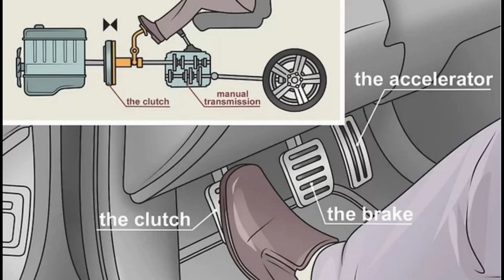Because of its high torque and low speed, first gear is not suitable for fast driving. The second gear provides less torque than first gear but allows the vehicle to move faster. It is often used in slow-moving traffic, gentle turns, and gradual acceleration after starting. The third gear is commonly used for moderate speeds and is well suited for city driving. It offers a balance between torque and speed, allowing smooth movement without excessive engine strain. Fourth gear is used for higher speeds and more open roads.